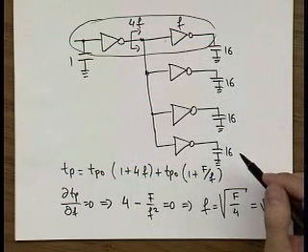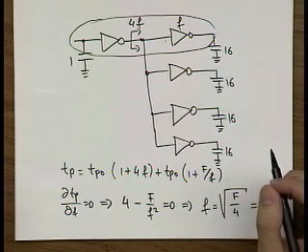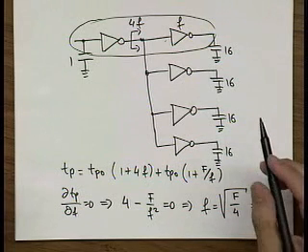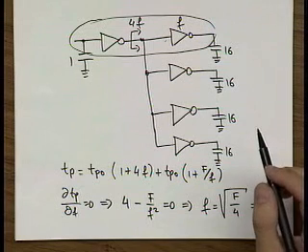What this means is that to make equal propagation delay in both stages, you basically have to have a smaller sizing factor due to this branching, and we'll get back to that in much more detail when we talk about logical effort and introduce the concept of branching.